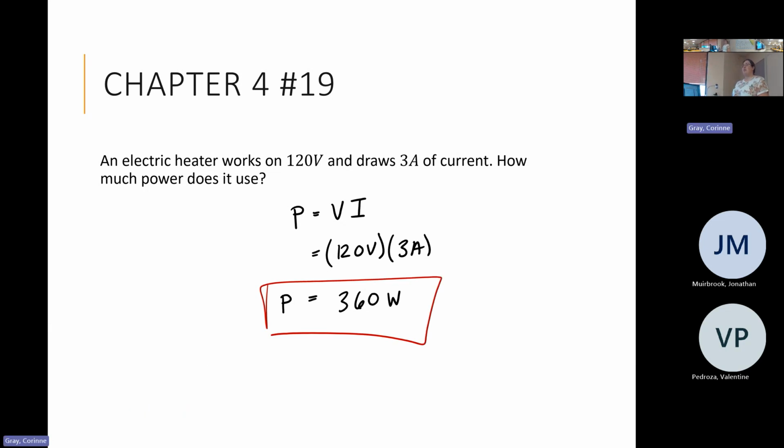This is pretty much the extent of how we will be using power in this class. So basically, a lot of the questions you'll see in the textbook, part A is going to be hard in comparison to B. A is going to be like, find the current through all the resistors. Then B's like, what's the power consumed by every resistor? In that case, you probably want to use a different power equation, but you could go through and use this one. You would have everything for it.